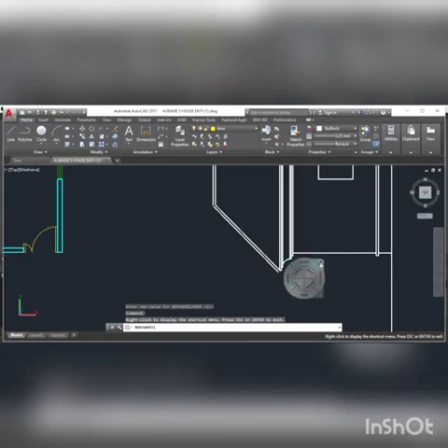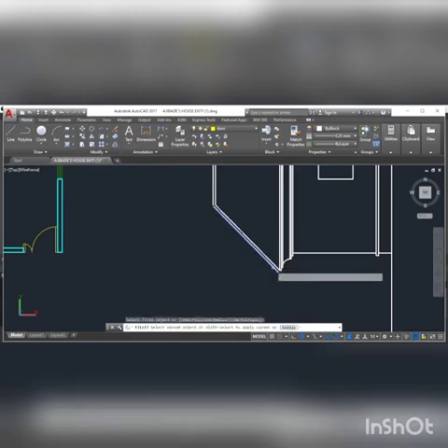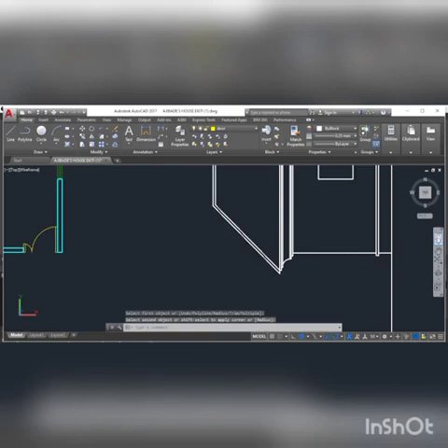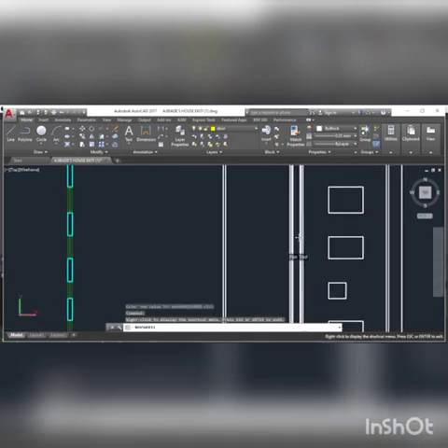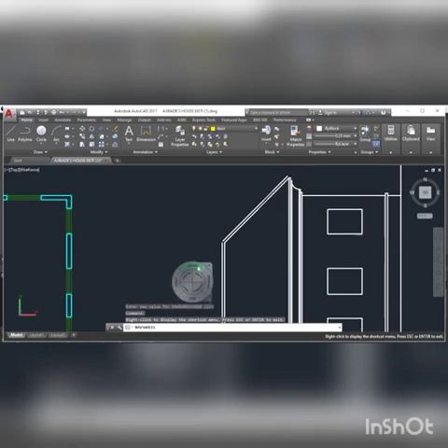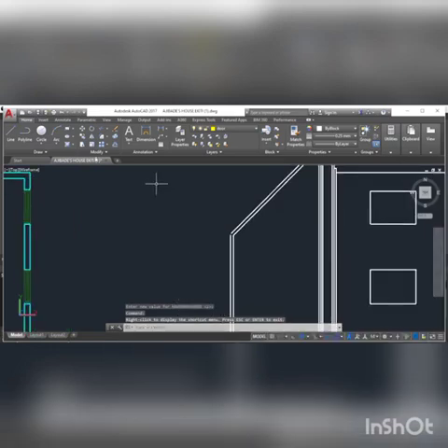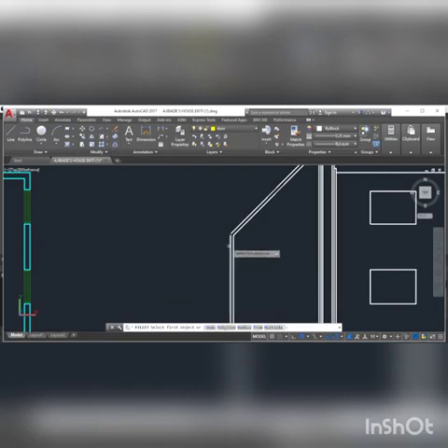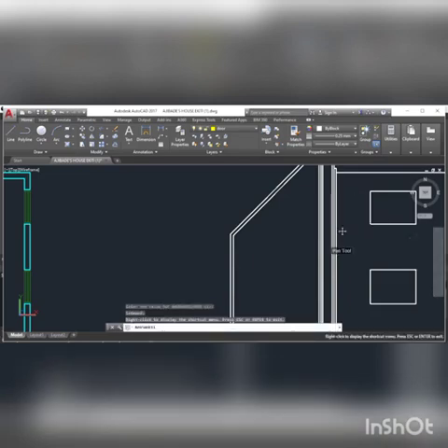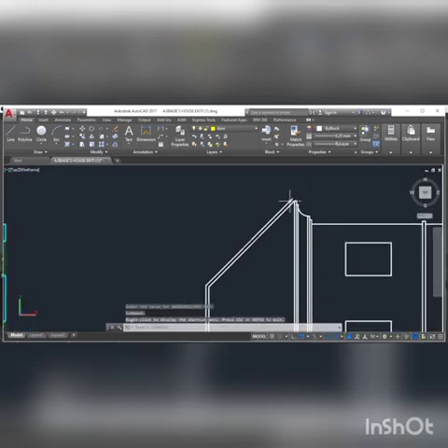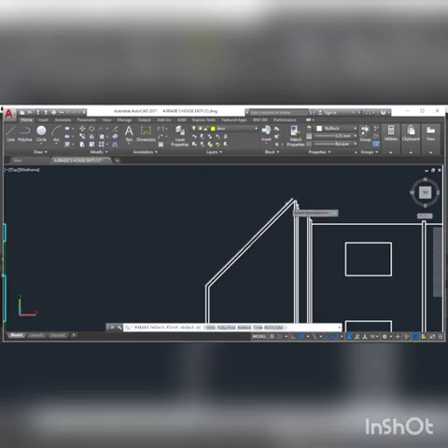Repeat the same thing on the other side. So pick fillet and chamfer again. Pick this point and this point to close it up. Then pick this again. Then pick this point and this point to close that up too. Then pan all the way down and zoom in. So we pick our fillet and chamfer again. We pick this point and this point to close it up. Then same thing applicable here as well. So our fillet and chamfer to close all this.